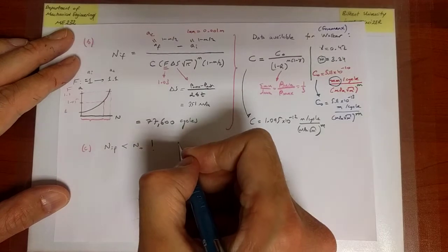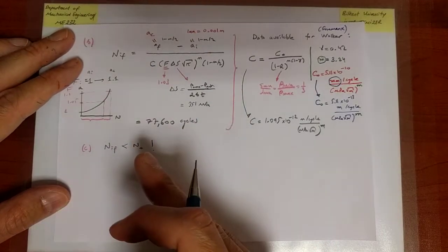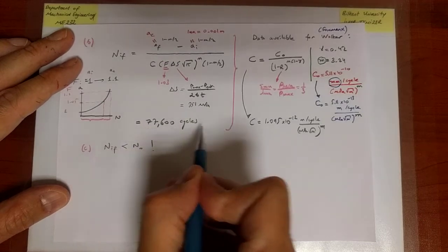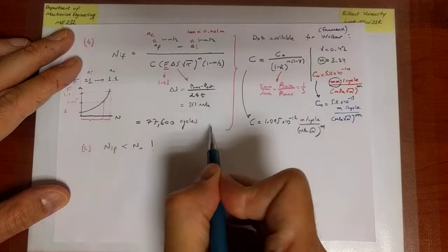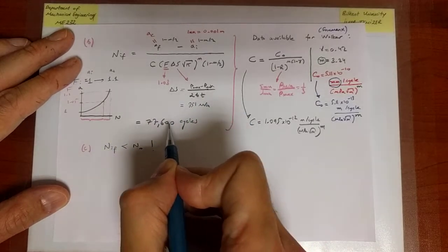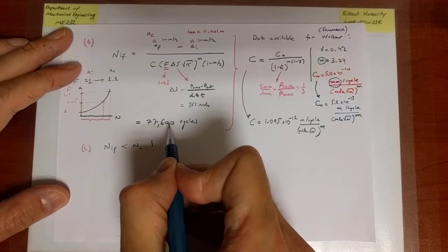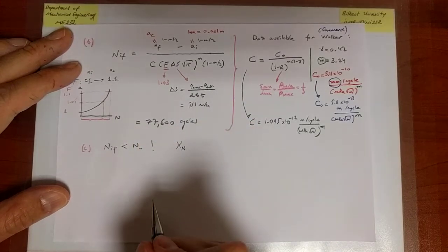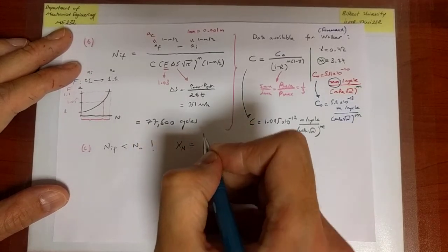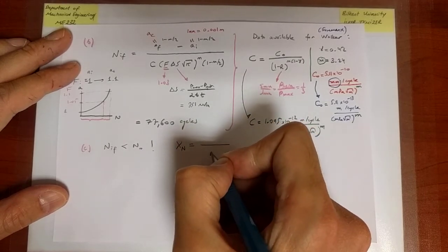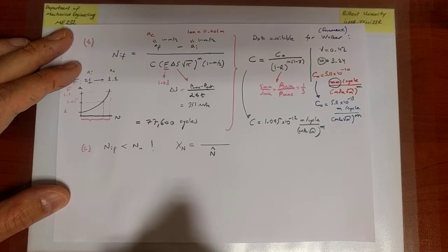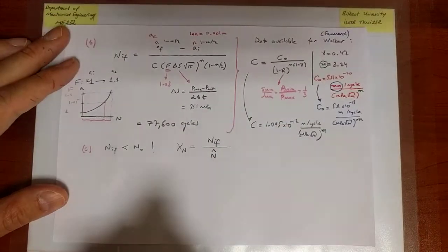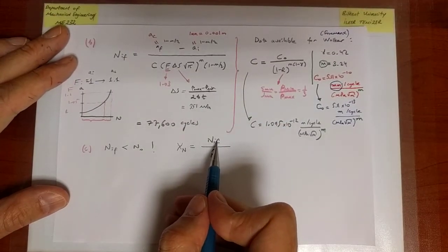So now we have a safety factor. When we apply the safety factor, we know that we will reach failure after this many cycles, so my safety factor will apply here. My service safety factor is going to go on top of this value for number of cycles to failure. So when I write the safety factor on life, which is a determination going to allow me to determine when I do service, the safety factor comes through not N_0, but rather from N_IF, because that is going to give me failure.